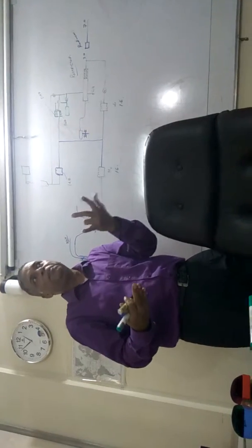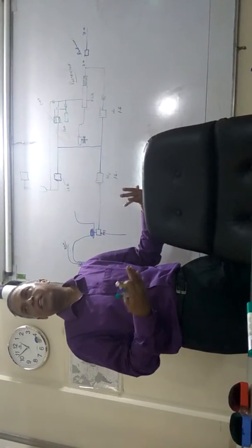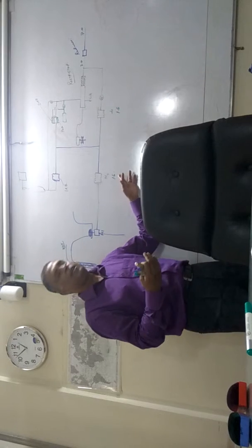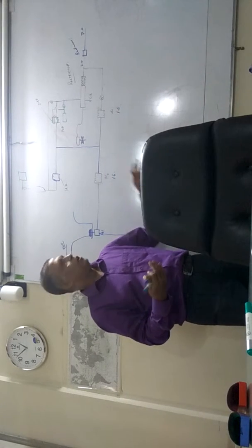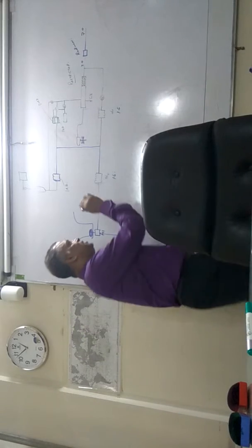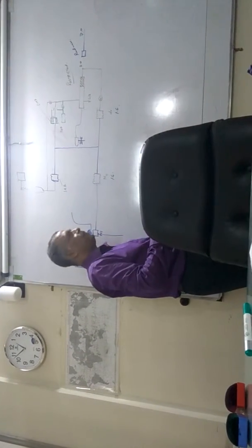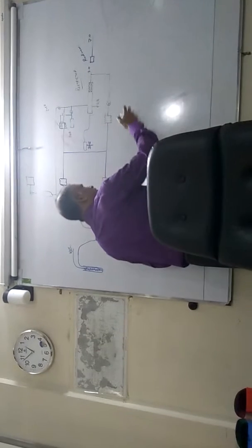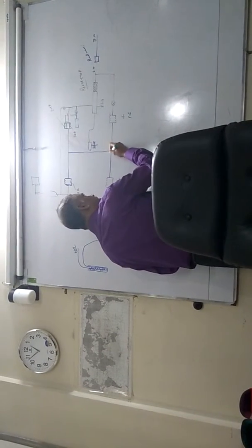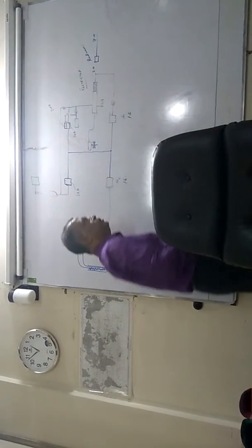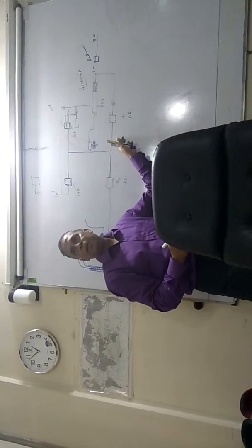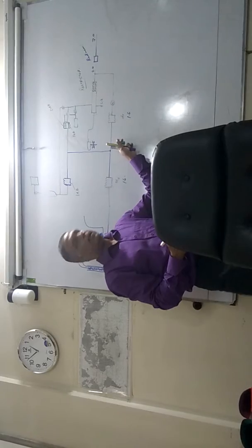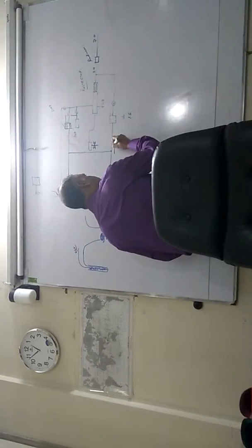You reduce the RPM, less load, lower temperature, and thereby lower pressure and higher pressure in this bellow. So if this pressure increases and that pressure remains the same, can this be in the same position, because this is a link between these two bellows? So from this side it will get more push, and there will be a motion this way, correct?